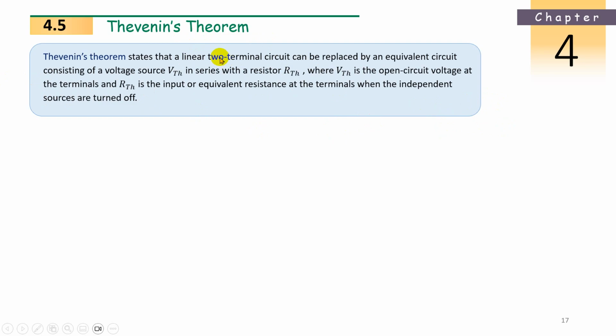So what it is exactly telling: it must be a linear circuit, maybe of whatever big size, we won't care about that. We just have to replace that circuit by its equivalent circuit with a Thevenin voltage source and resistance RTH in series to that voltage source. Then we can connect the load resistance whose behavior we want. Then we can continue. So how does it work?